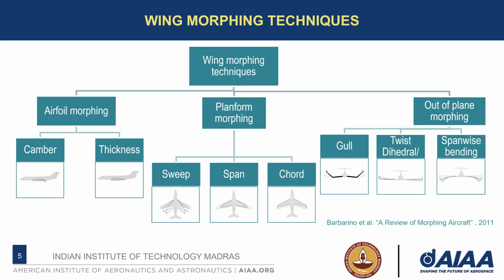Wing morphing techniques refer to the change in the shape of the wing during various phases of flight. In conventional aircraft also, we use localized shape adaptation, typically modification of the airfoil, in order to exert control over the aircraft and to provide additional lift during takeoff and landing, mainly at lower cruise speeds. But these wing geometry changes are limited, with narrow benefits. But a morphing wing with inherent deformability and adaptability can be beneficial for aircraft that operate in different flight regimes.